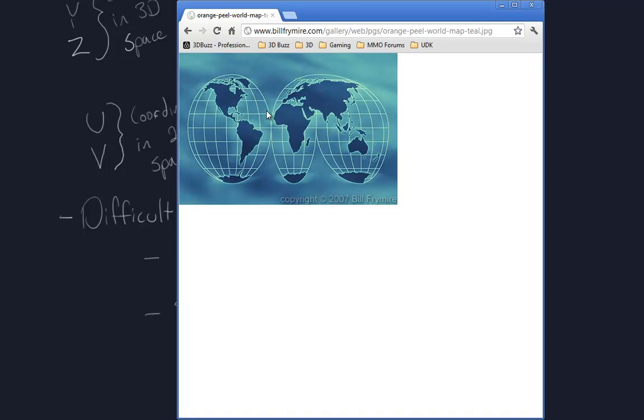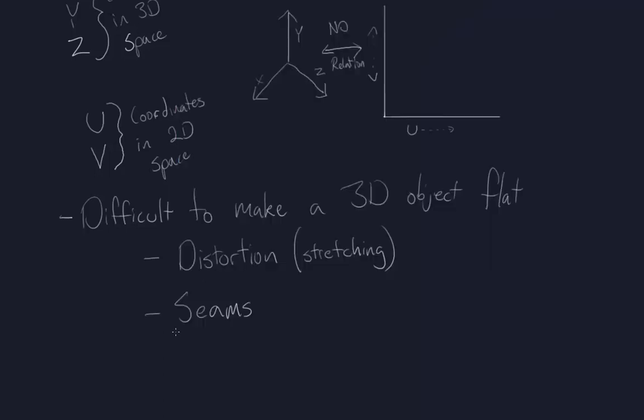And again, the same thing has happened. It's the same problem. We're trying to take something that is spherical, the globe, and flatten it out. But in order to prevent as much distortion as possible, we've made some additional slices that result in all of these excess seams. Now this is exactly how UVs work in 3D. As you try to lay an object out flat, to take it from 3D into 2D space in a nice clean manner, you will have to decide whether you want distortion or whether you want seams. And it's always going to be that way.